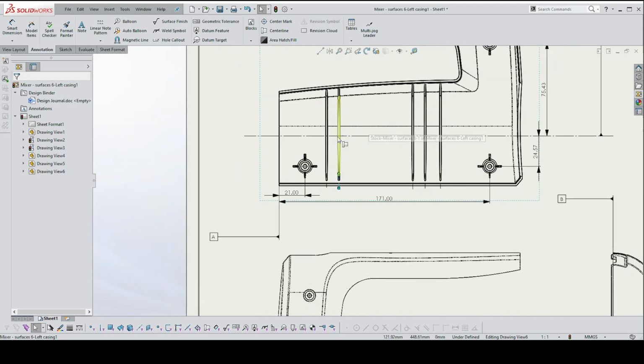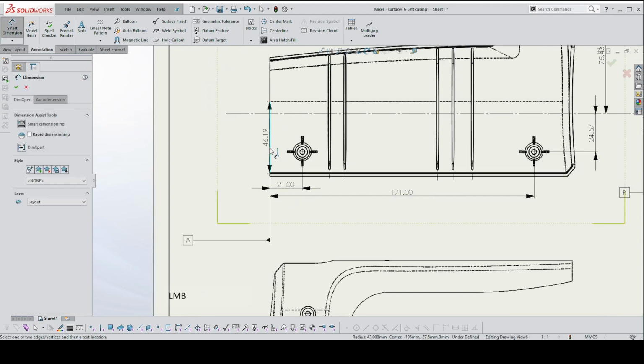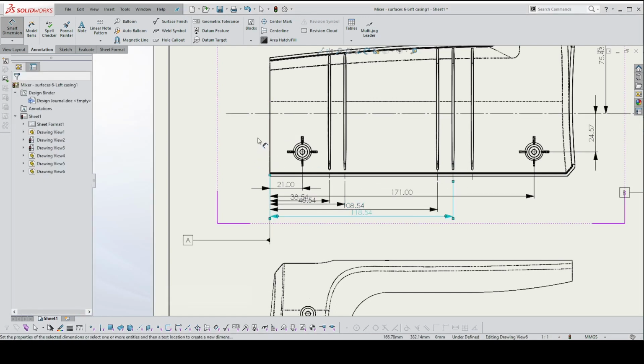Okay, so in a sense, I already have the position of the ribs because of this datum line having been placed in that center point. So I just need now the X dimension. So let's go back to dimensions. Let's go back to our starting point, our datum, put 1 in. And in this case, I'm not worrying too much about how I place these because I'm going to show you a neat trick at the end of this for arranging all your dimensions.